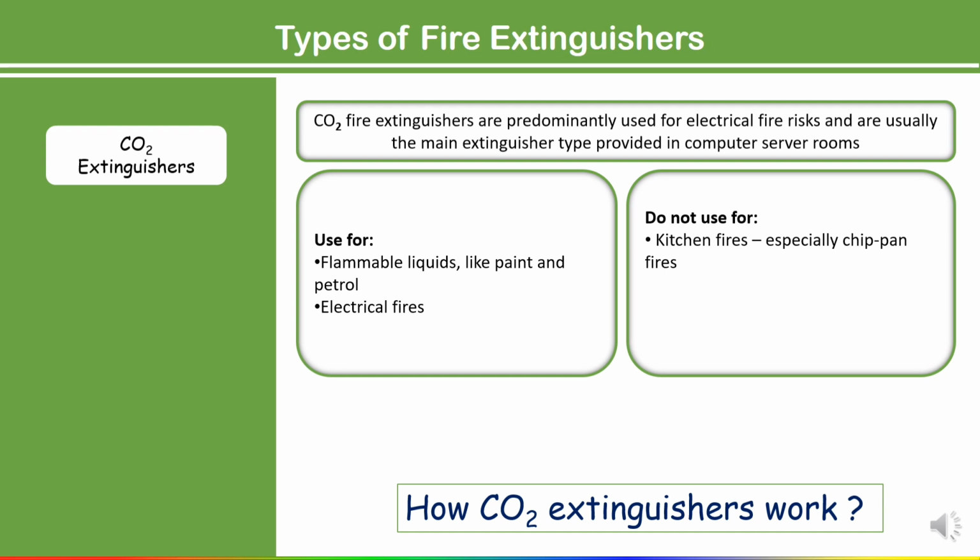So for oil and fat fire, CO2 is ineffective because it does not cool the fire enough and cannot create a barrier to prevent the release of flammable vapor. So never use it. You don't even need to use the CO2 for this combustible material.